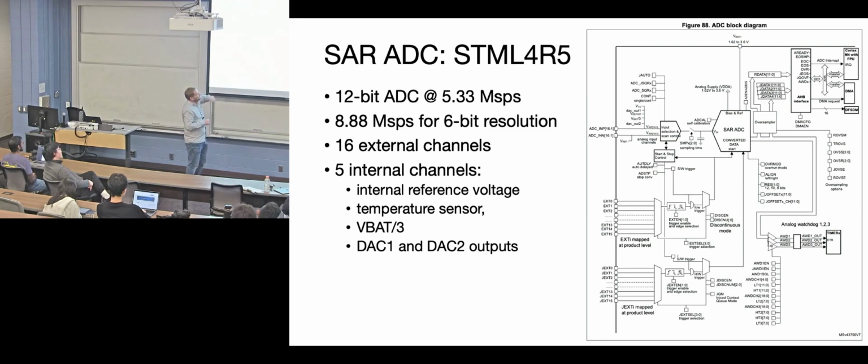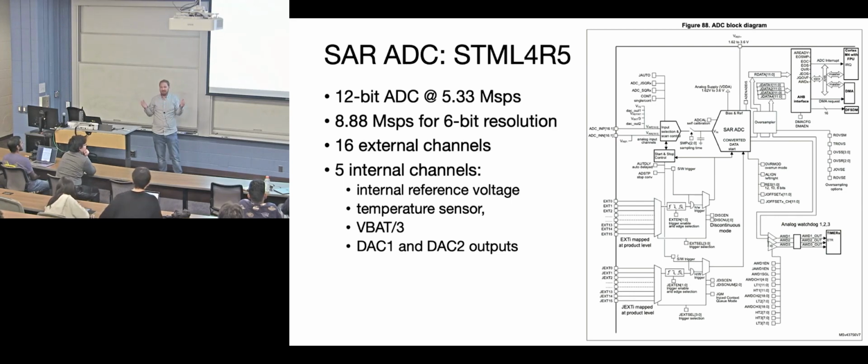There's an internal temperature sensor, which is read by the SAR ADC. Almost every piece of silicon gets a free temperature sensor. It's great. There's a trick where you take two identical diodes and put two different currents through them. You'd have to know what those current values are, and the voltage difference across those two diodes is proportional to absolute temperature, within half a degree or so accuracy. So almost any silicon device with an ADC, some way to take that analog voltage difference between the diodes and turn it into digital, will give you a temperature sensor for free.